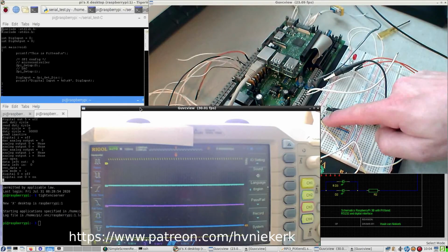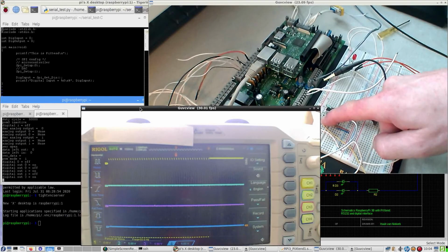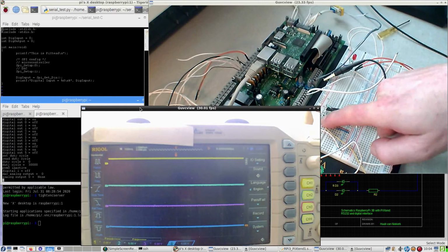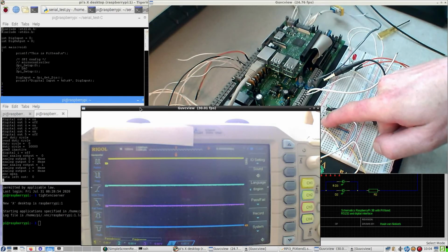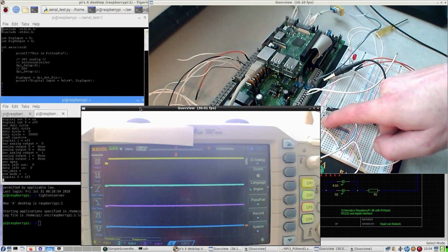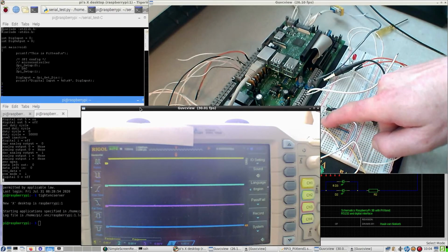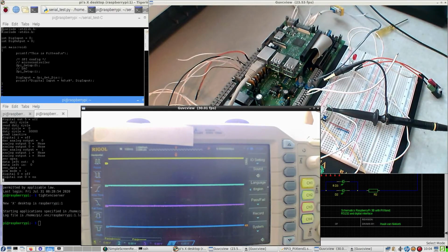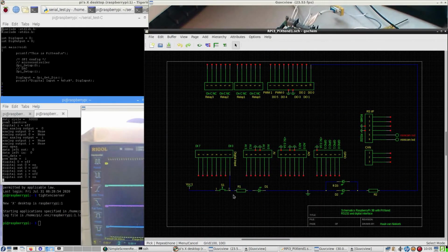So I am pressing the button and you see 5 volts. Actually slightly less than 5 volts. It's 2.5 volts, which is possible because of the resistor. Wait a minute, resistor, that means that the probe is oh wait, this is not entirely accurate.